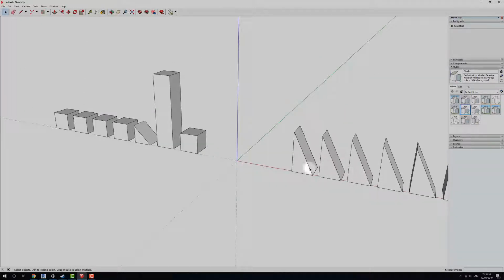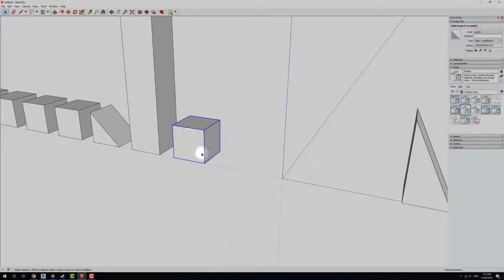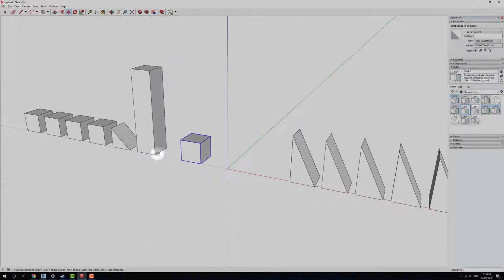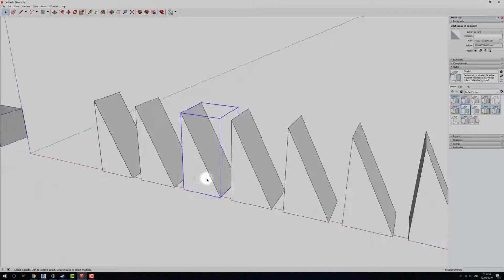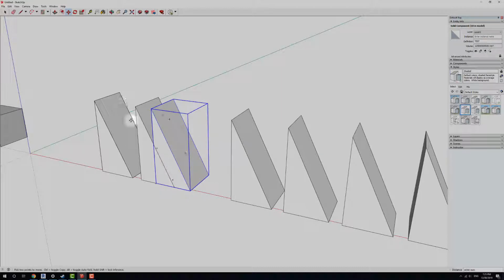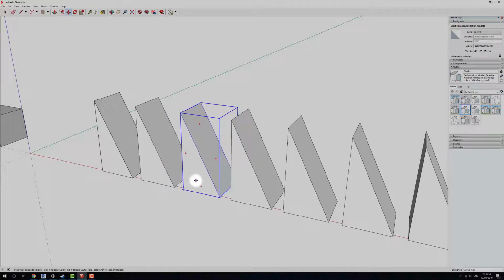Groups and components act very, very differently. Components will affect every other component that you've created, whereas groups are just grouped, and they will stop you from facing that stickiness. So if we look at this group here and move it across, notice how, even though they're touching, we can detach them very easily without having to conform to that stickiness concept. Same with your components. If I grab this and interlock these, I can uninterlock or remove them without having to conform to that stickiness.